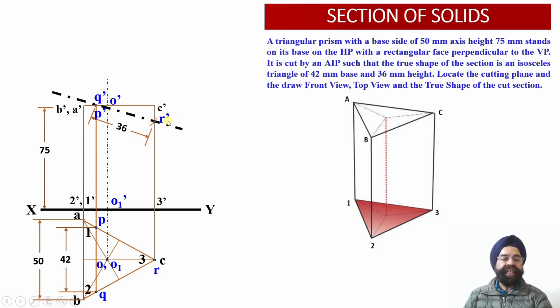Now having identified the point R' through which the auxiliary inclined plane should be passing, we can check one point of intersection we had obtained over here. The second point we have also obtained. So in order to draw this auxiliary inclined plane, we are going to use these 2 points. Obviously it is not a single point; here 2 points have already overlapped.